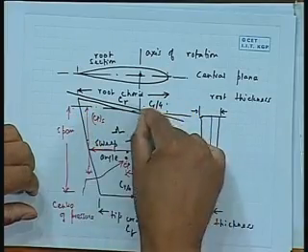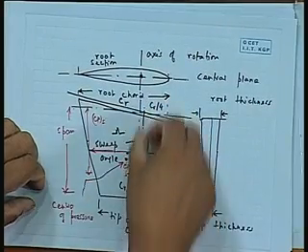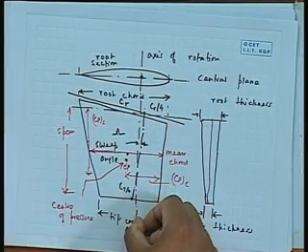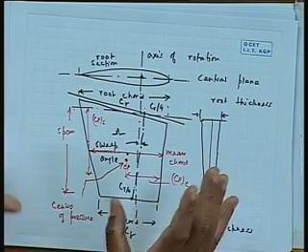That is done by taking 1/4 of this from this edge, 1/4 of this from this edge, and drawing this line and finding out how much this line is inclined with respect to the vertical. This is known as the sweep angle, which tells me approximately what is the orientation, what is the taper. That is all. It is simply one measure to find out how much it is tapered.